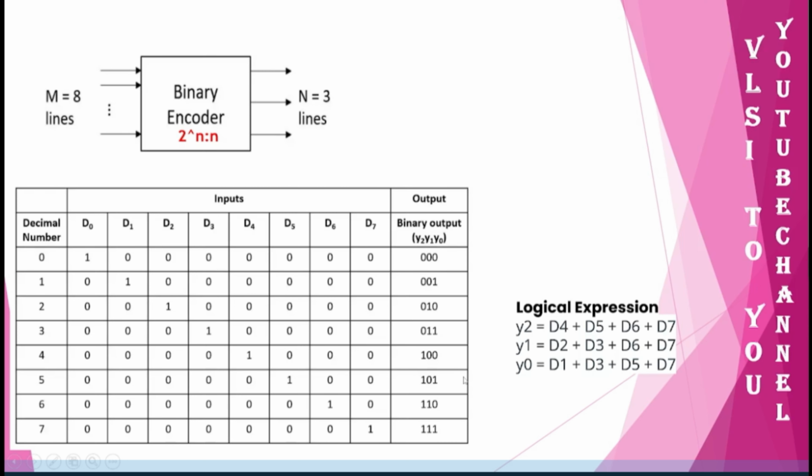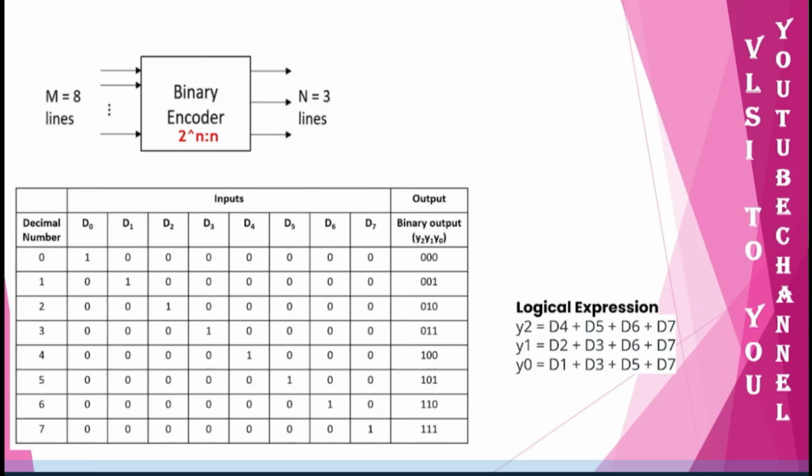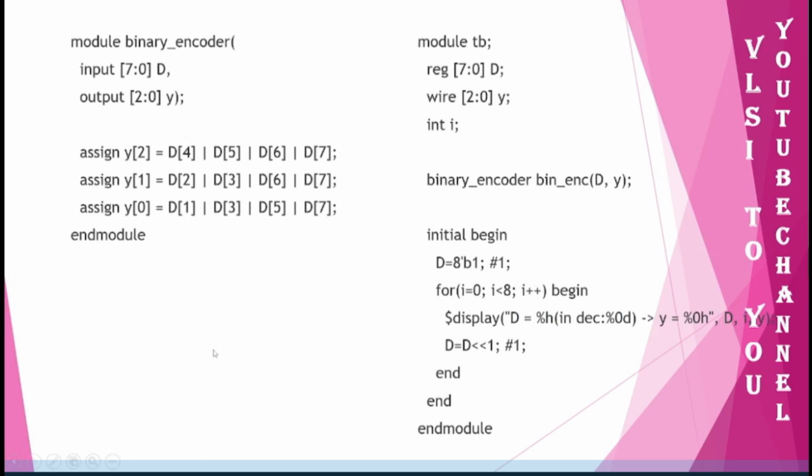And then after one time unit, again it will enter, again display, again 1 unit, again enter. So instead of giving all these things, I have just given it in 2 lines by using the for loop. This is how you can reduce the logic in the test bench also. Instead of giving all the values in a blunt manner, try to make it as simple as possible. This comes when you practice. Your practice in writing the for loop, your practice in knowing the shift operators, depending upon this experience, the shortening of your particular code will come.